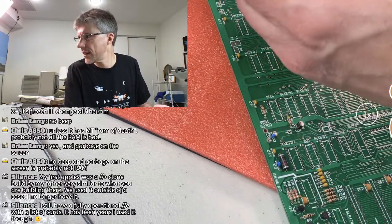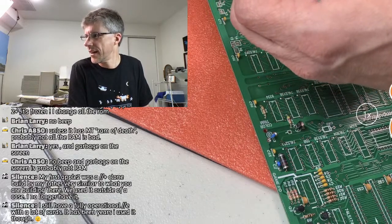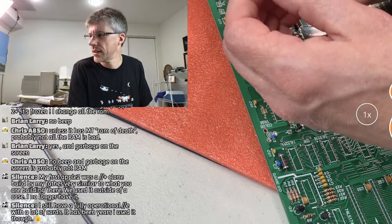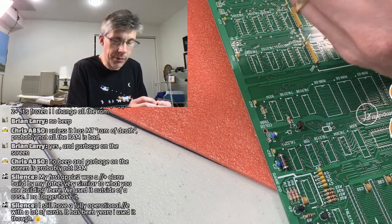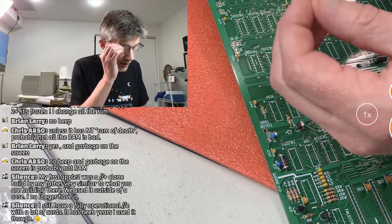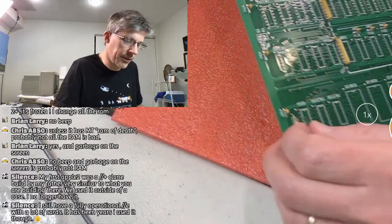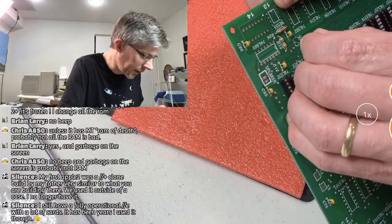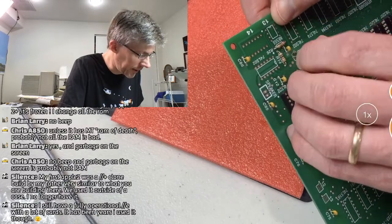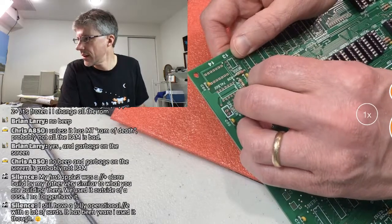Let's see. No beep. Okay, so that's what Brian says. And garbage on the screen. So yeah, and Chris is pointing out that's probably actually not a RAM problem, because you don't need much RAM at all to start up the Apple II. Pretty much as long as you have one working RAM chip, it'll be okay. So the RAM is probably fine.